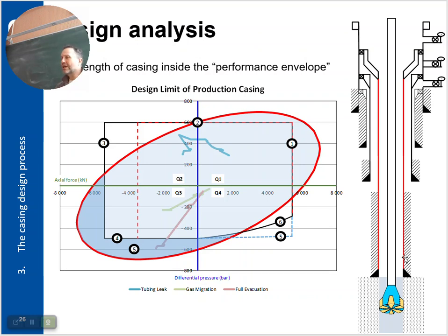You can talk about the kick and so on, but normal drilling loads are not that demanding. If you put in fracturing and well interventions, then yes, those loads can be extreme, and sometimes even set the design basis for some tubulars. But normally it's the production loads